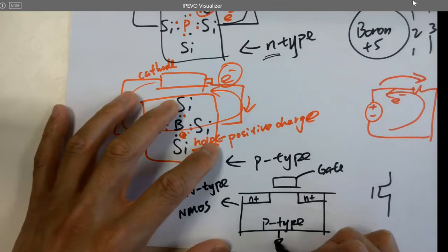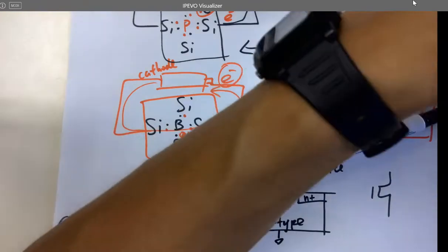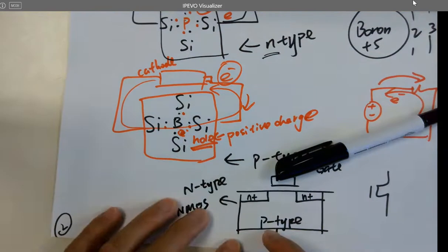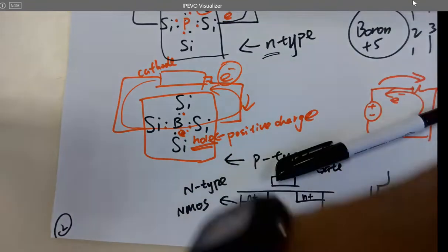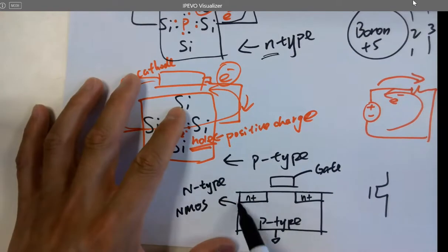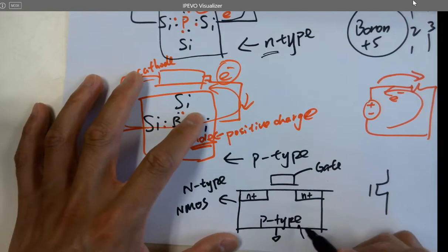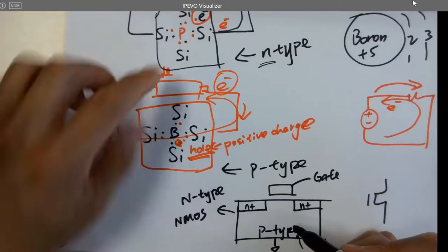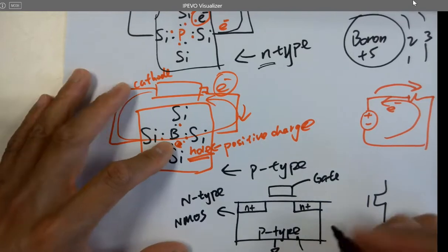So the p-type substrate, that's just a silicon wafer itself. If you got a silicon wafer, it can be an n-type substrate or a p-type substrate, but the p-type is the most popular one. So we got a p-type substrate, in TSMC or Samsung, right? They have a wafer, and then start doping materials onto it. So first, they got a piece of silicon like a p-type, right? So what's the dopant in the p-type semiconductor? This, right? Okay, and the p substrate, or it's called p sub,